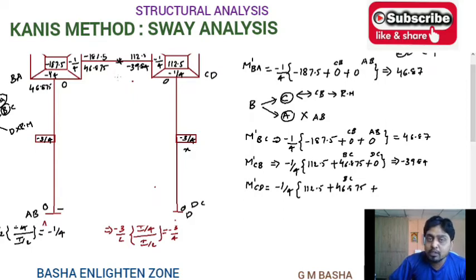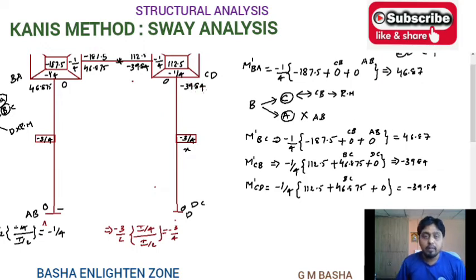For BC it will be 0 because there will be no displacement factors in the beam portion, and for DC it will be 0 because for the first trial you won't get any displacement factors. If you simplify, again you will get the same value. If your rotation factor is different, automatically the values change here. You won't get symmetrical values like this.